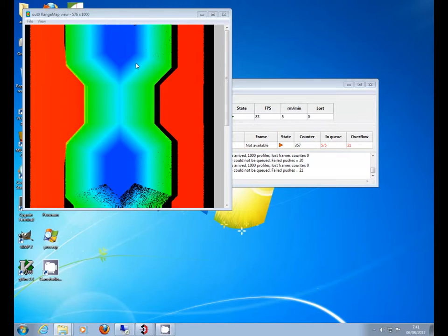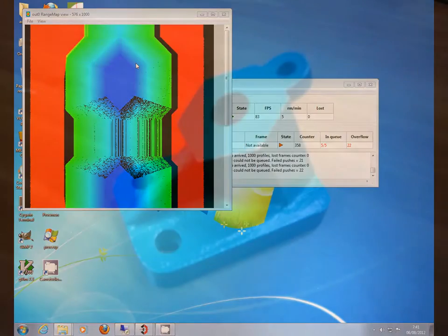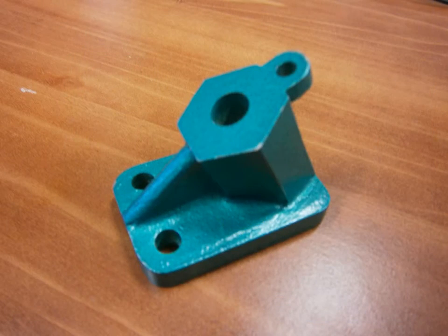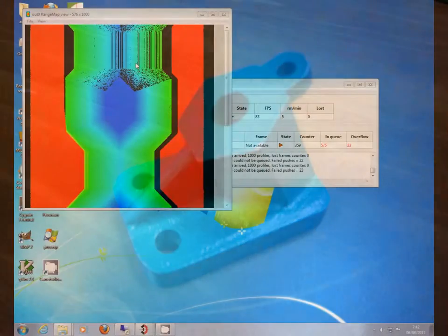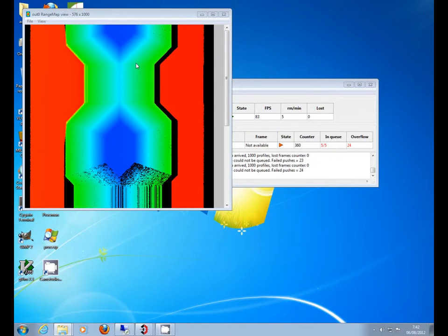But let us change the pattern now that we have already calibrated, for a piece that we will use to do some test measurements. This piece has an inclined plane, and it has a hole in this plane. So as a test, we will try to measure the diameter of this hole. To do this, we will align this inclined plane to the Z plane using our tilted Z map, and then we will pass this over to Sherlock to further analyze in 2D.